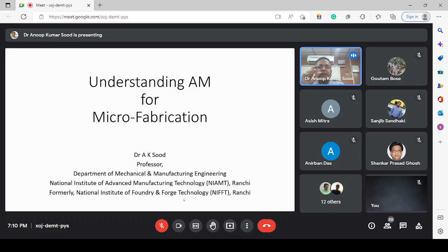Now, a triangle is represented using its 3 vertices. At the micro scale level, where my component is at micro level and has features at sub-micron levels, I am representing those things with a triangle having 3 vertices. These 3 vertices need to be spatially distinguished. At that micro level, these vertices may have some precision value which my software may or may not be able to read accurately to distinguish them as spatially different. It may happen that all 3 vertices collapse into one, and instead of getting a triangle, we get a point. So, is it a right approach to represent a CAD model in a triangular representation for the case of microfabrication?